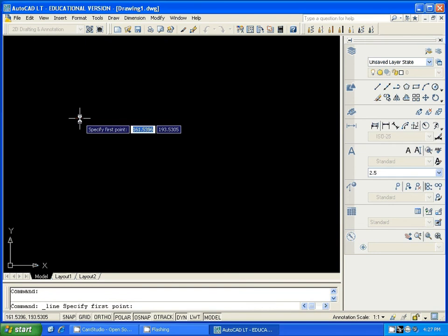In this video, I want to talk to you about dynamic input. At the bottom of the screen, you have your choices for snap, grid, ortho, and so on. If you keep going down, you'll find dynamic input. So in order to make dynamic input work, you need to toggle it on, and then select a command like